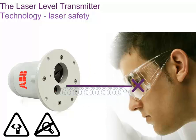Do not view the laser directly with optical instruments like binoculars, telescopes, or magnifying lenses. The aiming laser is visible to the human eye. This laser is rated Class 3R, which makes it bright and easy to see, but should not be looked into directly. This laser only works at installation and after a restart for a duration of 2 minutes to allow positioning of the laser level transmitter, and can be turned off completely.